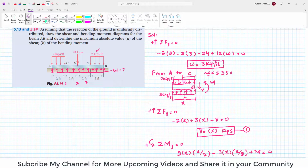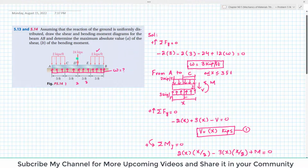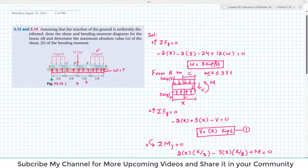So the load, you can calculate the load over here as well, and you will find that this load will be in symmetry. Using symmetry you can evaluate the load over here, shear force over here, and bending moment. It will be the same as we calculated over here, but the sign will change. Now let's move and draw our first part, that is to draw the shear force and bending moment diagram.